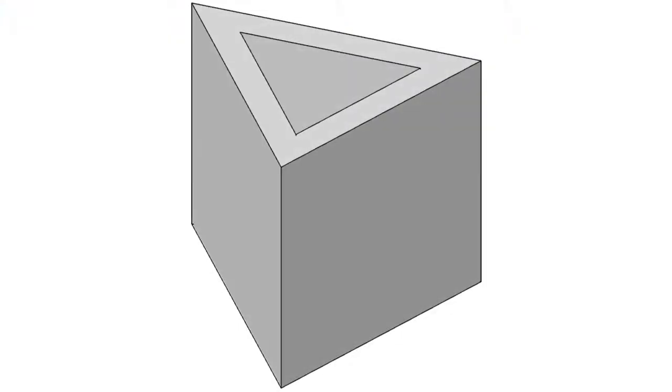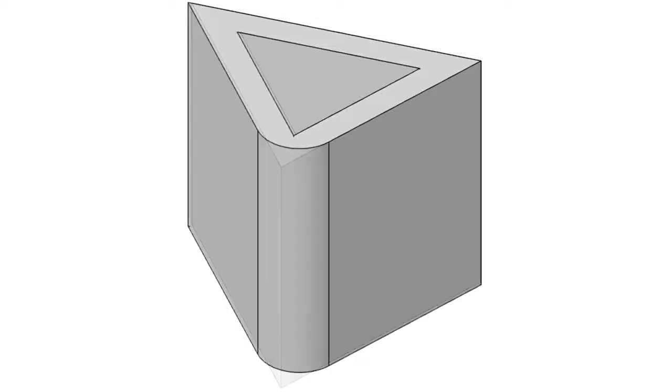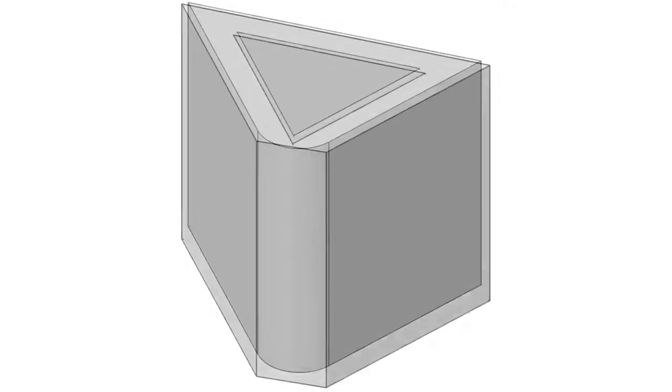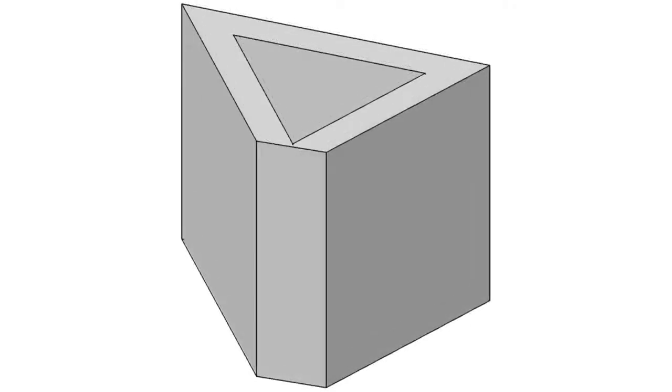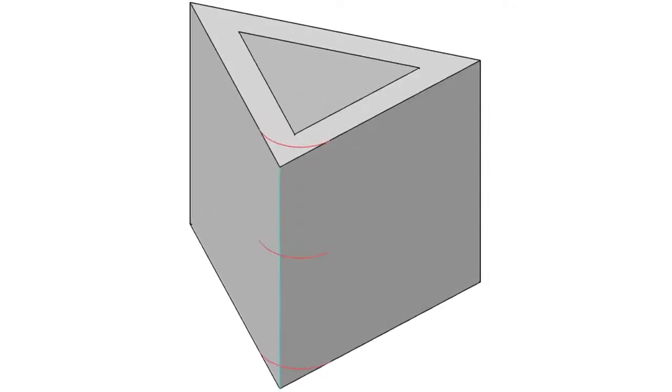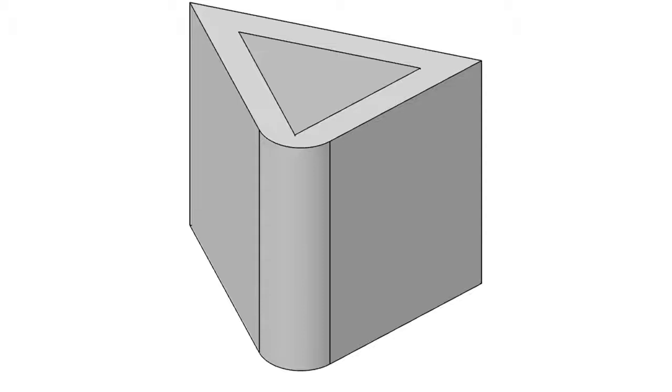One of the most common edits made in solids modeling is to fillet or chamfer edges. Filleting means to round the edges, while chamfering means to apply an angle. The nice thing about nanoCAD is that it shows you a preview of what the radius of the fillet or the angle of the chamfer will look like before you finish the command.